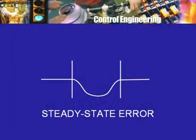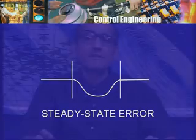We will see also that if one does not look at it very carefully, one may conclude that that drive results in steady state error, although it does not. So, I am talking about an automatic controller which will control the field current of the generator, which will result in adjustment of the field current of the generator in such a way that when the load torque has changed, the speed will go back to its steady value.